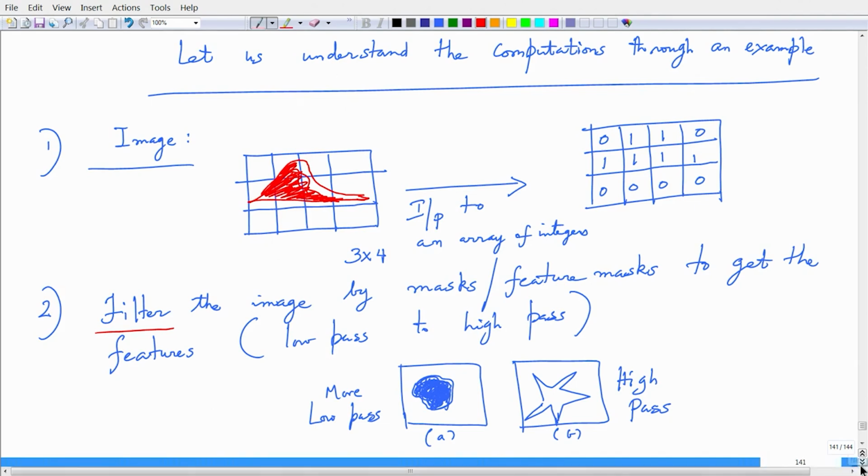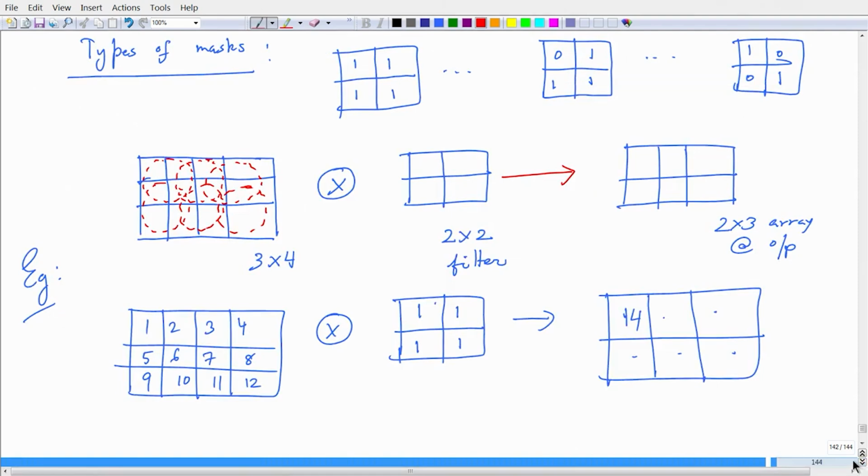Now, what do we think of when we imagine these masks? Let us imagine a 2 by 2 mask. This is essentially low pass, it has all ones, it is doing an averaging operation. So, I take this mask and slide this over an image, I have a low pass operation. Similarly, I can have band pass operations by controlling what ones have to be flipped to zeros, so on, to what I can have to be a true high pass mask.